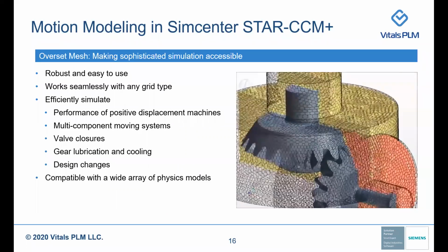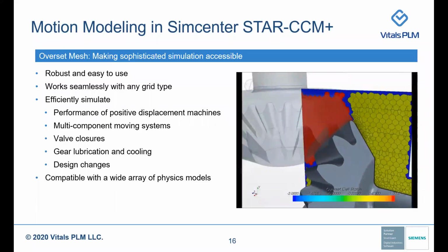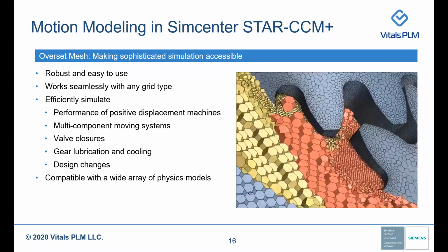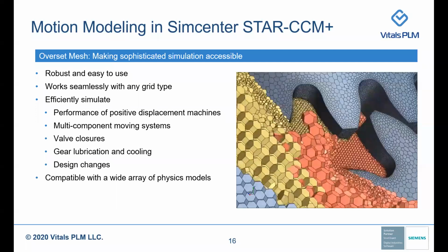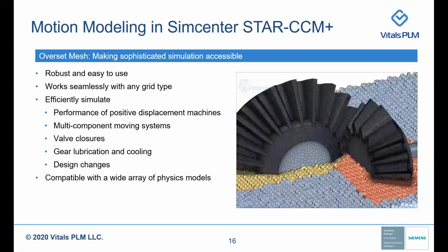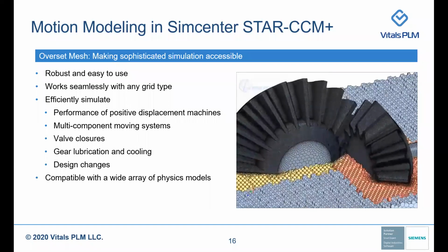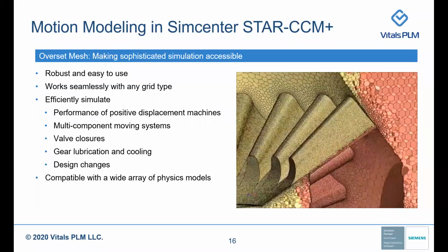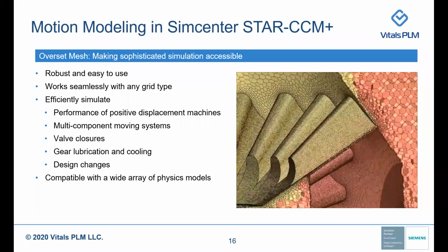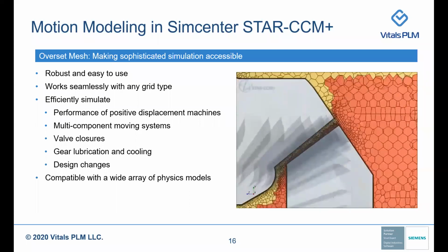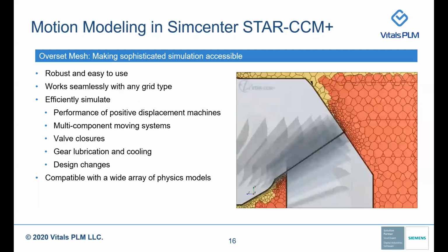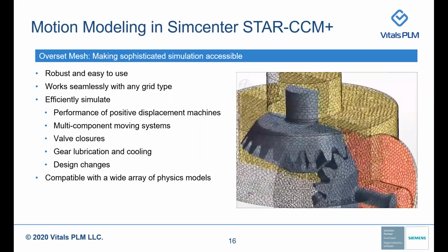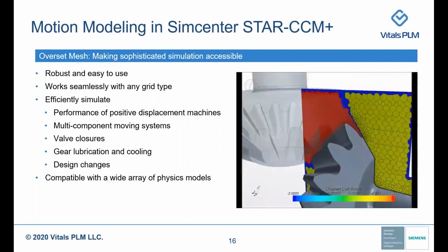So in this session, we are mainly focusing on both Overset and DFBI as part of all the key requirements which we just covered in the previous slide. The Overset Mesh implemented in STAR-CCM Plus is very easy to use and very robust. It is supported by all the grid types in STAR-CCM Plus. As you might know, STAR-CCM Plus has different grid types, namely polyhedral, trimmer, tetrahedral, and can efficiently